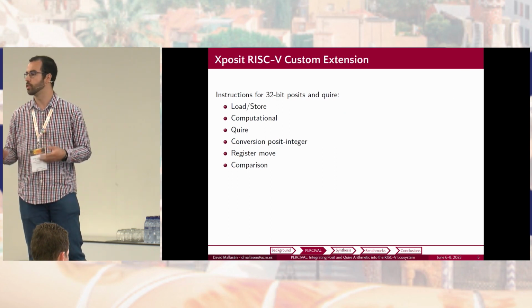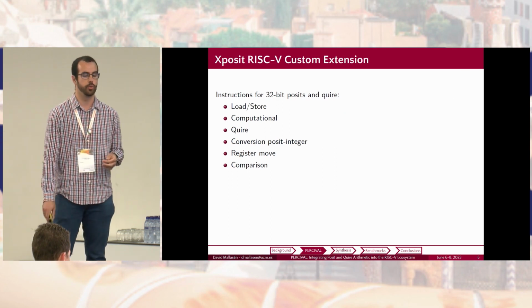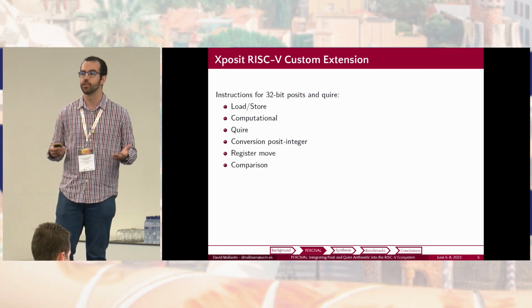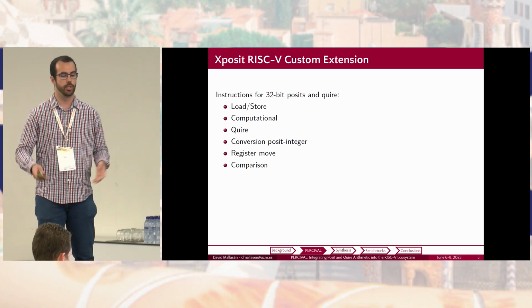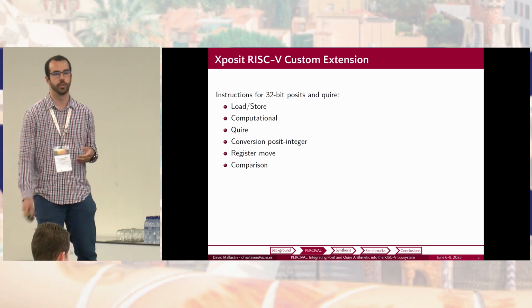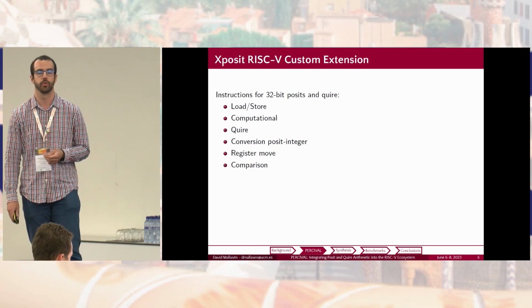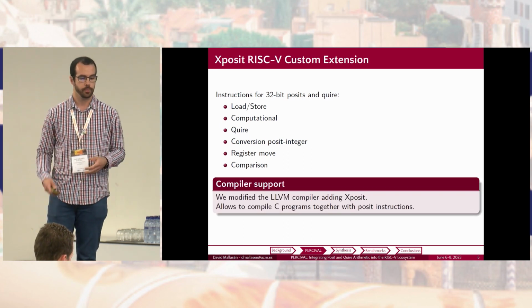also computational instructions, which is add, subtract, multiply, divide, square root, etc. Operations involving the Quire accumulator register, conversions to and from integer numbers, register move operations in the CPU, comparison of posits. So we have the full spectrum of instructions that you need to operate with floating point numbers.